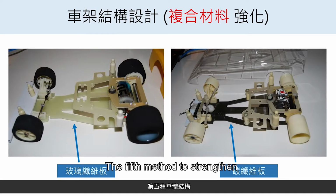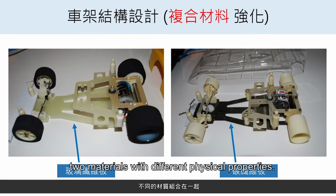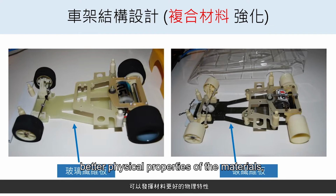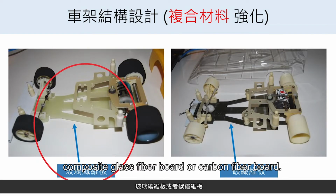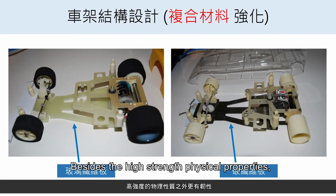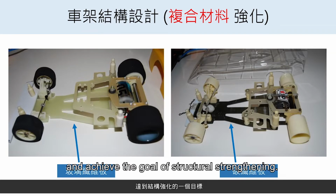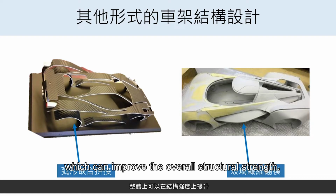The fifth method to strengthen the car body structure is to use composite materials. Composite materials are made by combining two materials with different physical properties. They can complement each other and bring out the better physical properties of the materials, such as the commonly used composite glass fiber board or carbon fiber board. Besides the high-strength physical properties, they have more toughness and can withstand greater external impact and achieve the goal of structural strengthening. Two other structural design forms are provided here, which can improve the overall structural strength.